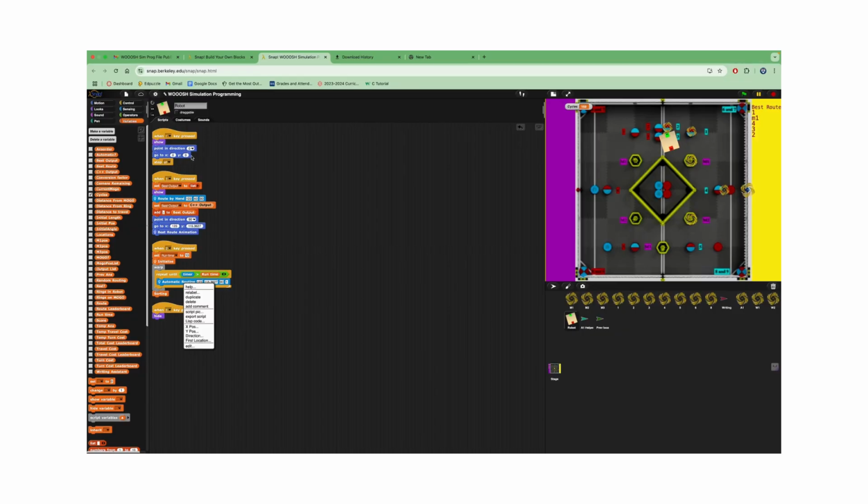This shows in the upper right hand corner, and you can take those routing things, and when you press 1, you go back to 1. Oops, I'm on the wrong starting Y. We want 115.3627. In the upper right hand corner, we can simply press 1 to go into the manual routing, and we can input these as they appear in the right hand corner. And there we go. And I say done. It'll animate it for me.